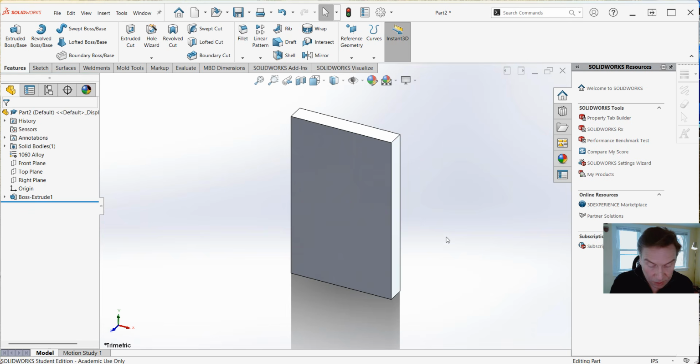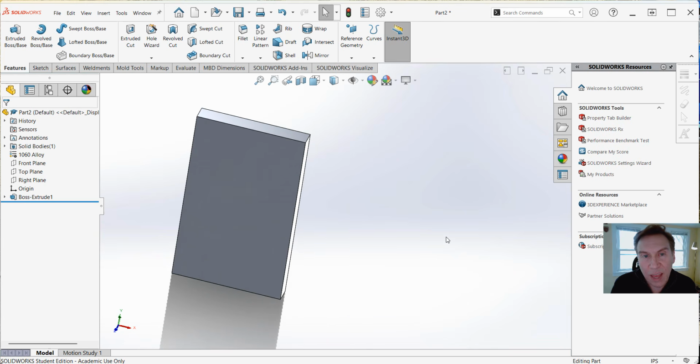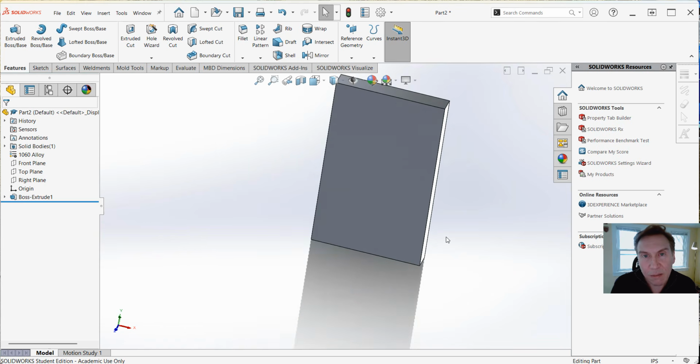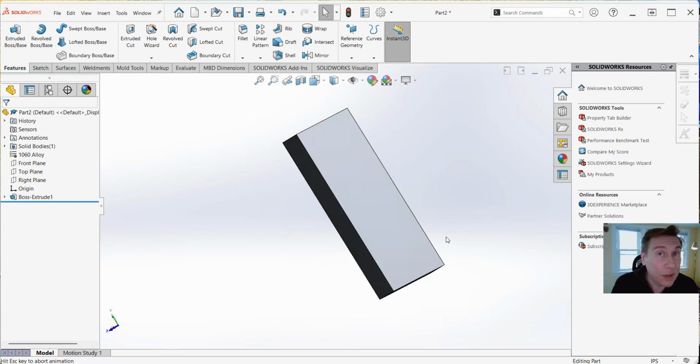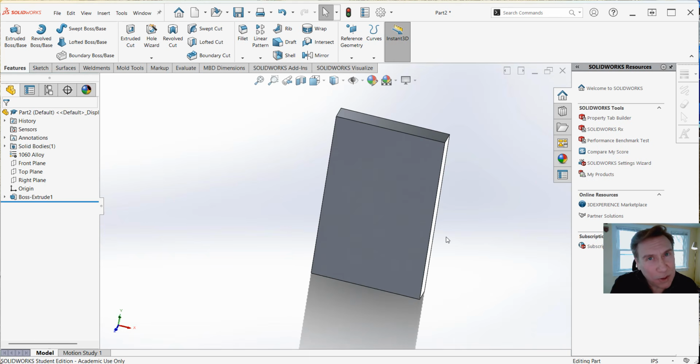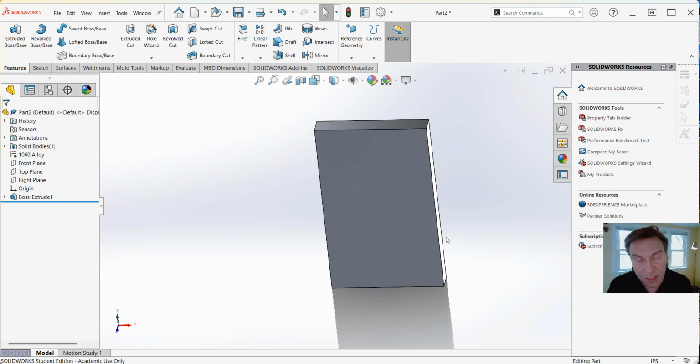On your keyboard, your arrow keys, go ahead and click on your left arrow key. You'll rotate left, your right arrow key, right, in 15-degree increments, up and down. Now, if you hold Control and hit the left arrow key, that's pan, left and right, up and down. If you hold Shift, it'll rotate in 90-degree increments. I don't expect anyone to remember this stuff, but you could always come back to this video if you want. Alt rotates clockwise and counterclockwise. And that's with the arrow keys. So there you can see there's a number of tools.